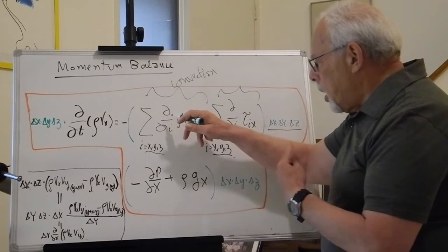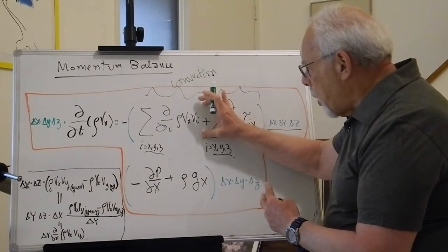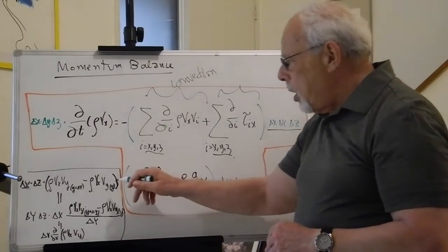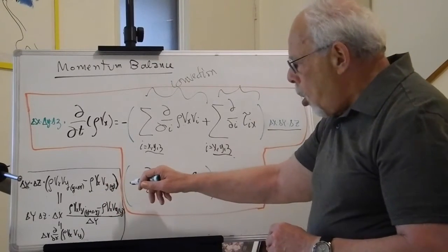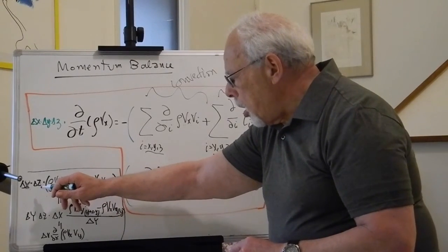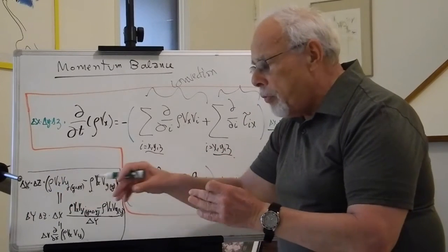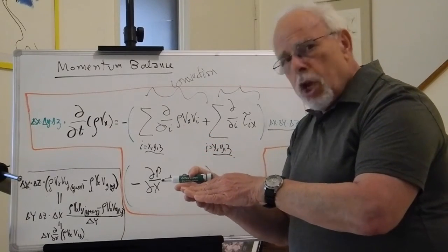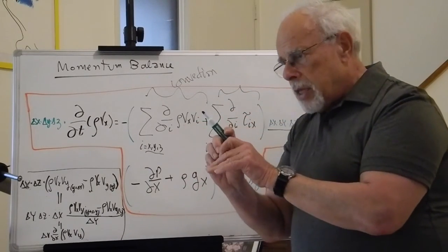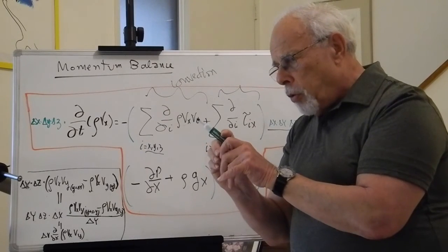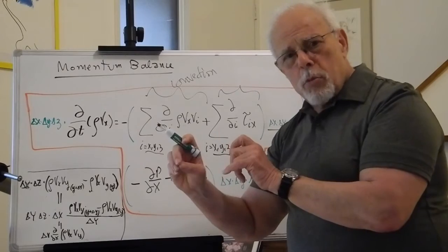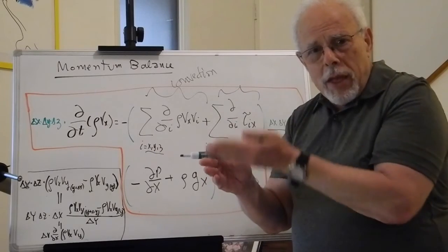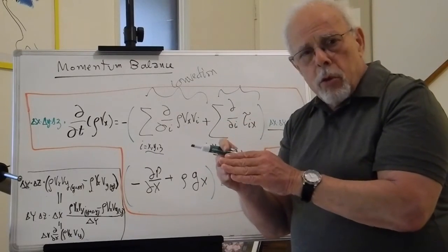This is the summation of the convection, which, just to recall what we have done a minute ago, accounts for the migration of the bulk that flows through the y direction. But it's fluid that we account for in its x direction momentum. It flows up because it also has a vy, a velocity in the y direction. But we account only for the momentum in the x direction.